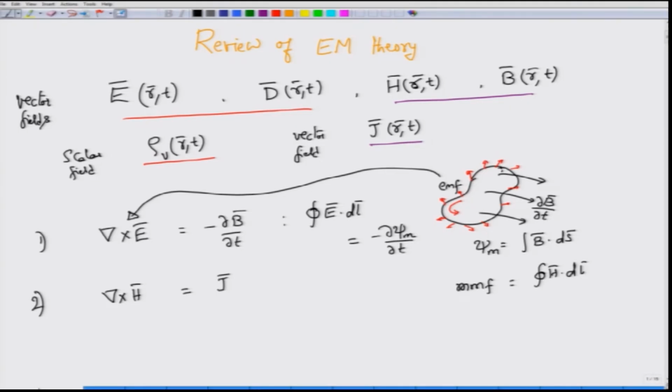It was originally thought that this curl, or the magnetomotive force MMF, is only because of the current density J. However, later Maxwell added a very important term known as displacement current density. Displacement current density is the time rate of change of electric flux density D. So, the time rate of change of this electric flux density D will act like current, and it will continue the current wherever conduction current is not possible, conduction current being the J vector.